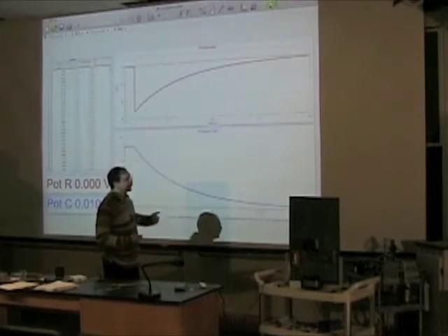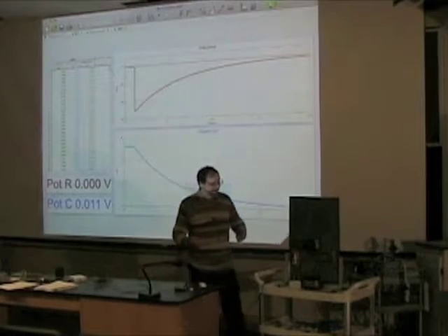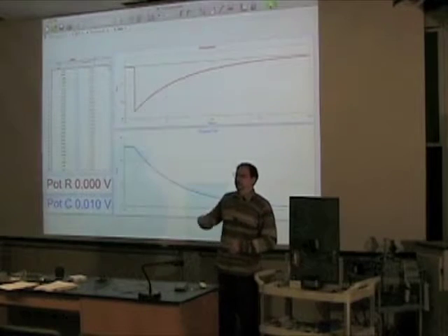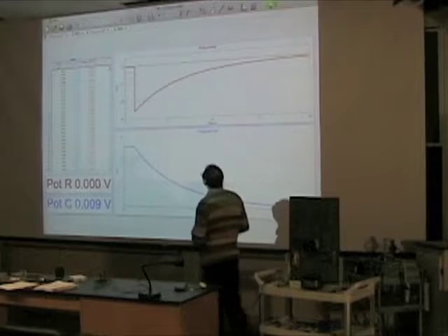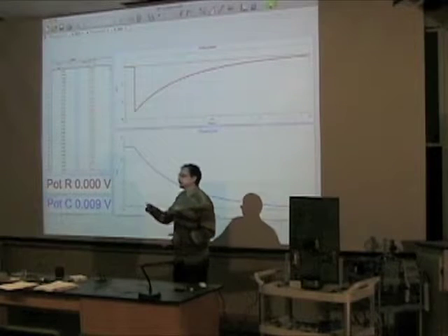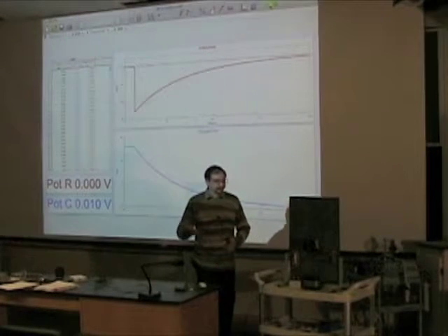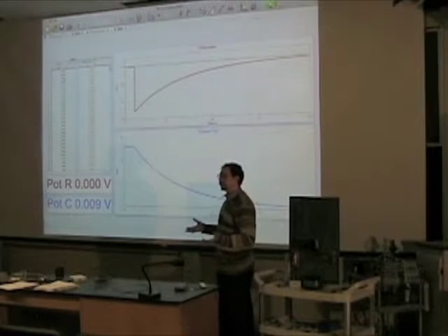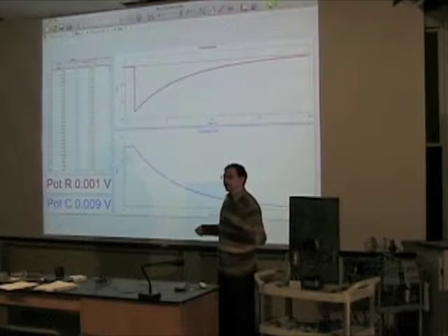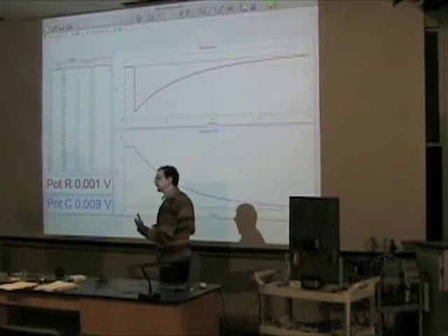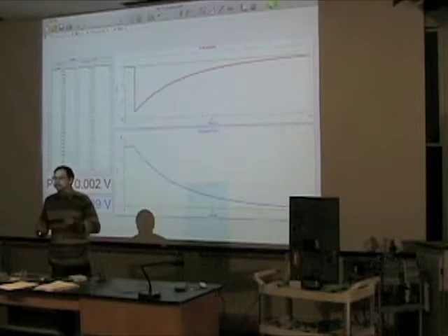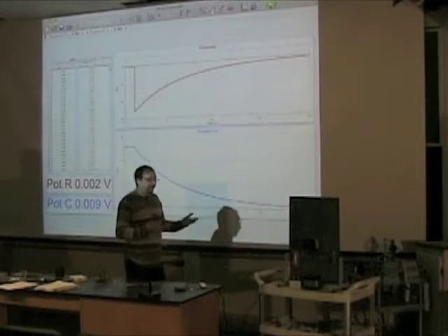And what is happening to the voltage across the resistor? Well, as soon as I close the switch, it jumps to the maximum value. And then again, it gradually goes to 0. Why? Because when the capacitor discharges, it loses eventually all the charge. At its initial instant, we could treat the capacitor as a battery. So we could apply Ohm's law, where voltage, resistance, and current are related.